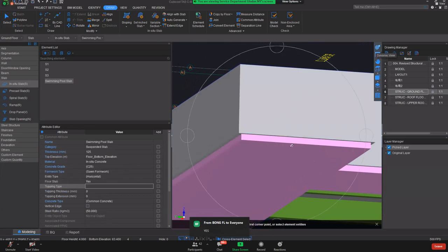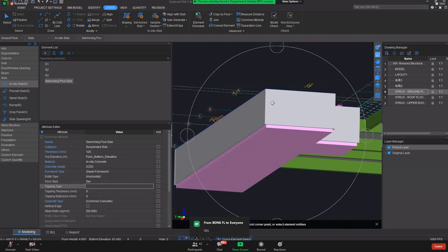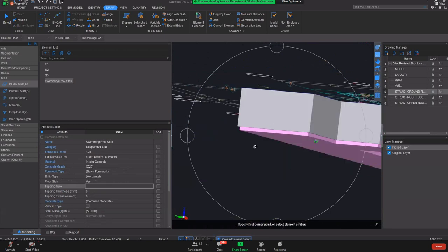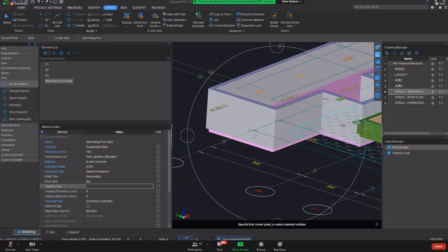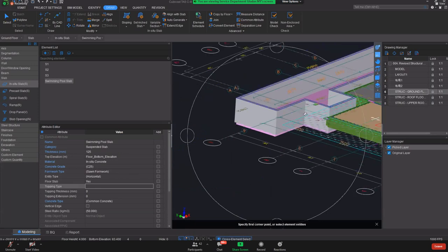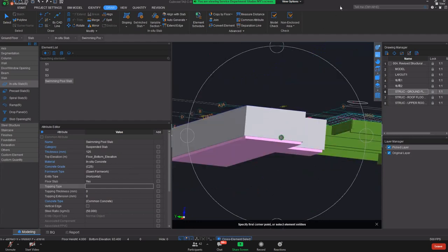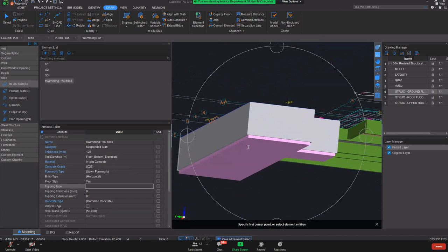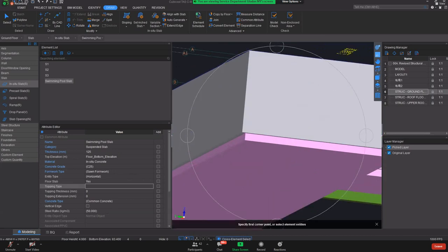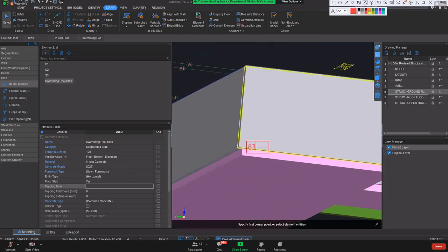Xiaomei, right? Okay, so just now the wall under the slab, the slab you already set minus 1.45, right? And you can see in the 3D, what we set for the wall elevation just now was 83.4, we minus 1.45.